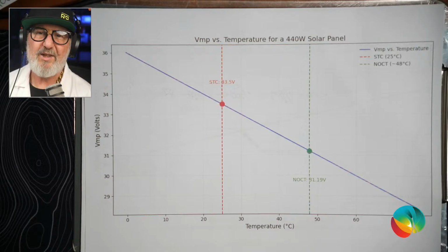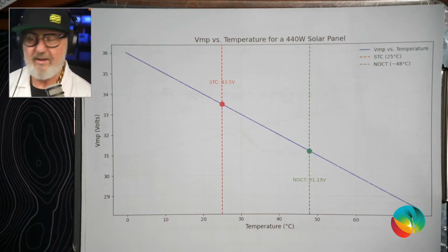And string inverters have a startup voltage. Basically, they'll want to get to a certain open circuit voltage before they'll even start drawing current. So, figures around, say, for a single phase inverter, 120 volts, 125 was fairly typical for a startup. And when I say startup, at that point, they'll try to draw some current and immediately there'll be a bit of drop in array voltage as it tracks along the load line of the IV curve.